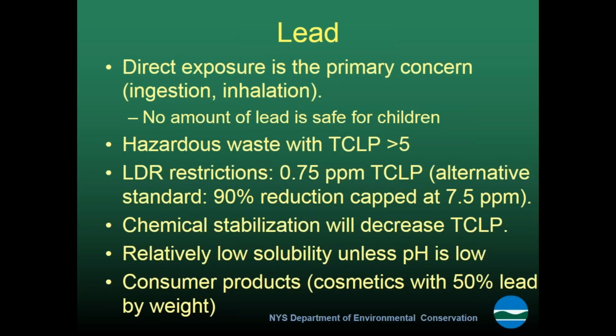Unless you have really low pH, lead has a relatively low solubility. So we're generally not looking at large plumes of contaminated groundwater when we're looking at lead-contaminated sites. You can have lead in the groundwater if you have high concentrations in the soil, but you can also get much higher levels in the soil if you have some acid conditions. One of our biggest sites is a battery recycler, and they do have some acid conditions that contributed to the groundwater conditions there.